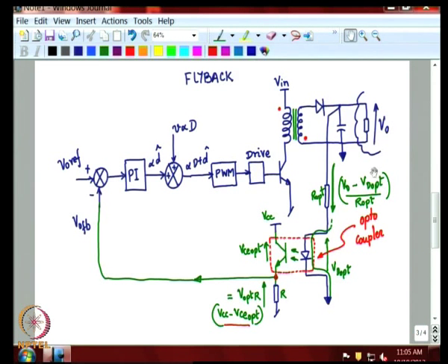As temperature varies, this value varies, and therefore, the current varies, and therefore, the bias point here varies, and therefore, the output that is fed back here. So, even if the voltage here V naught has not varied, because of the temperature variation, this value would have varied, and the controller thinks that the output has varied and tries to set it to a different value. Therefore, in order to compensate for the temperature, normally another component is included. So, before that, let us clean up some of these things here.